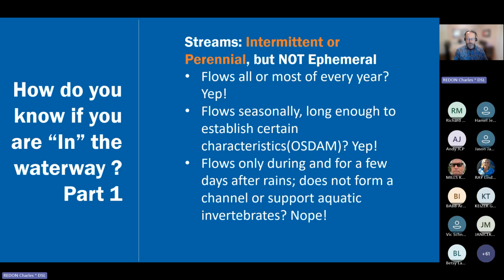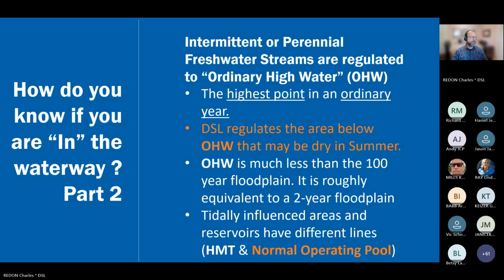And then, of course, rivers that are flowing all year round. Where do we regulate within those? Well, we regulate to what's called the ordinary high water. And so where you are in summer might be standing on a dry bank, you might still be within the river as far as the purposes of removal fill law.